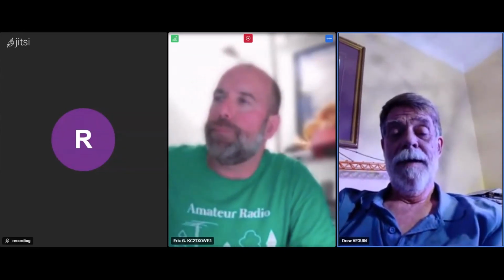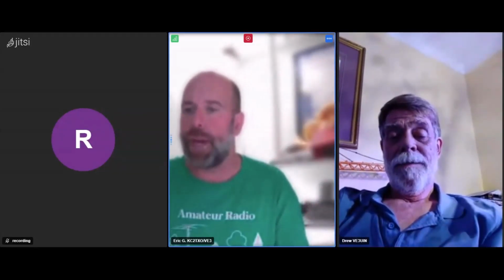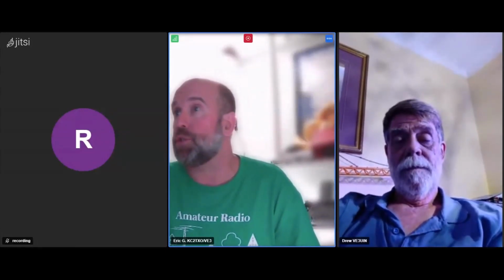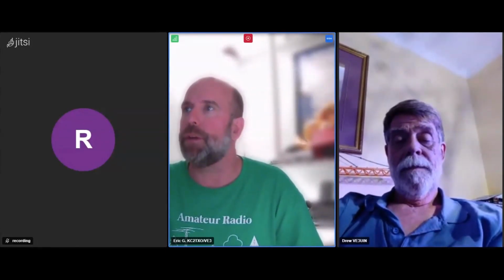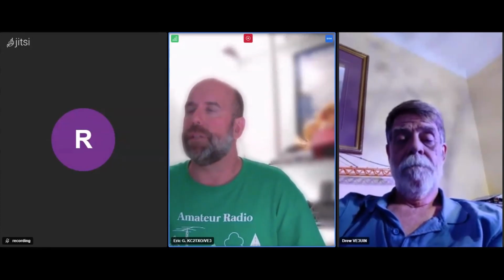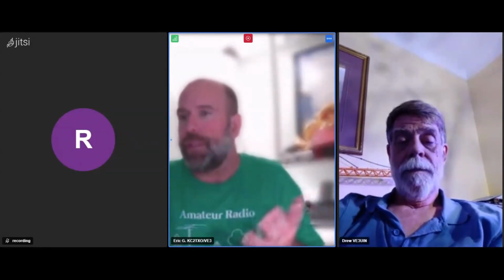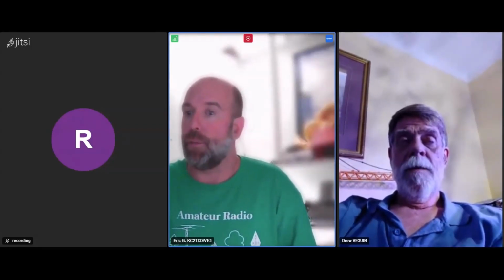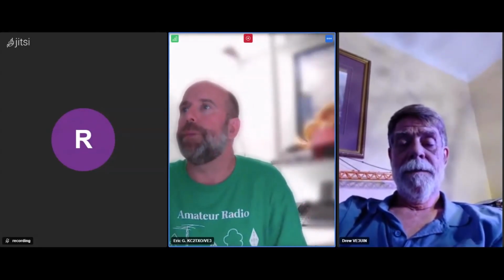Well, on field day, we ran everything. Ken brought his LDG AT200. That's what we were running everything through. We basically just turned the tuner off on the 7300, because the AT200 can handle a higher SWR, and I think that's what saved the day. Otherwise, the radio won't match anything.